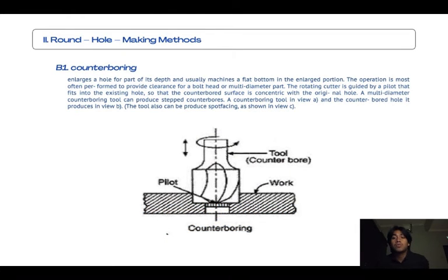So in drilling we have two subtopics. The first one is counterboring. So counterboring enlarges a hole for part of its depth, and usually machines a flat bottom in the enlarged portion. The operation is most often performed to provide clearance for a bolt head or multi-diameter parts.